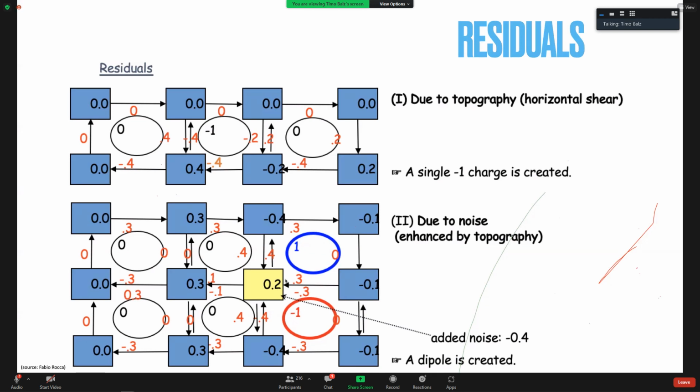Then we can say this is a residual of the phase unwrapping, and we can try to fix it, for example by creating such a deep hole and trying at the end to fix these residuals, right? If we have only one dimension, we can't do that. But with two dimensions, we can go around and try different paths and different directions to connect them.